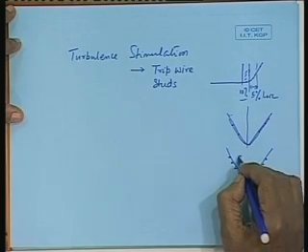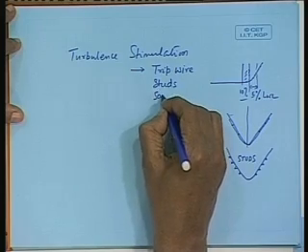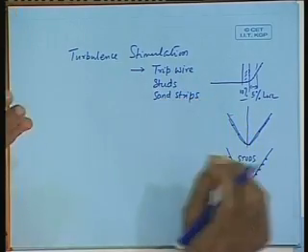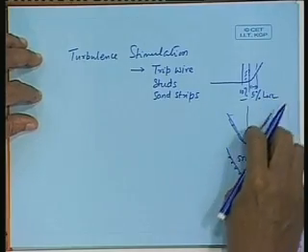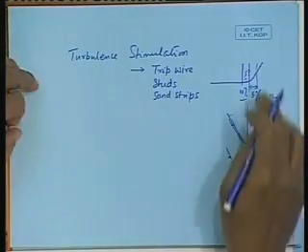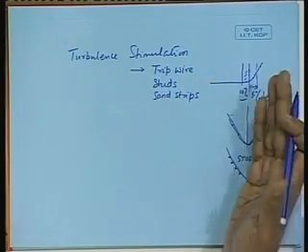These are studs, or we may use sand strips, sandpaper strips. Small sandpaper strips may be fixed around the ship's girth at the forward end at 5% aft of FP and 10% aft of FP.